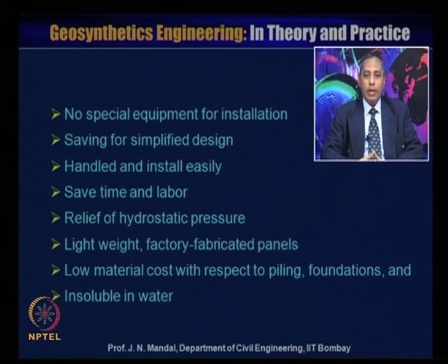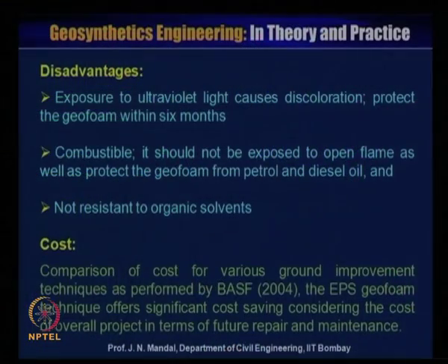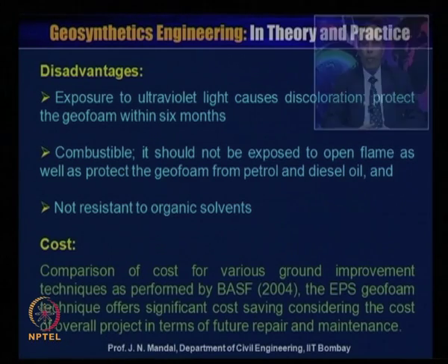It is a lightweight and factory fabricated panel. So as you like, you can have it, and also you can have it in different densities. Low material cost with respect to piling foundation, and insoluble in water. So every material has advantages as well as disadvantages. This Geofoam material also has certain disadvantages.